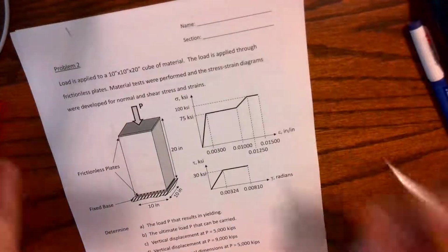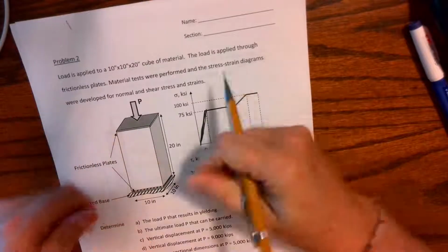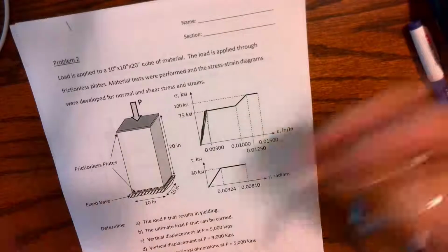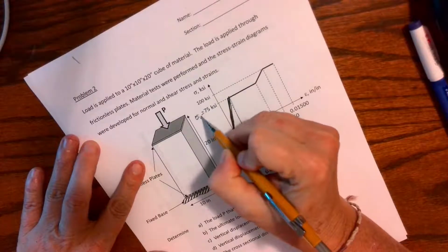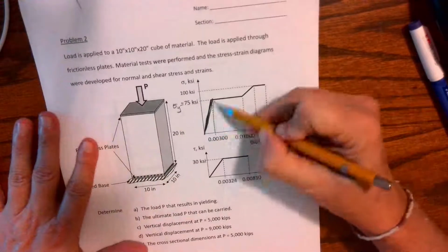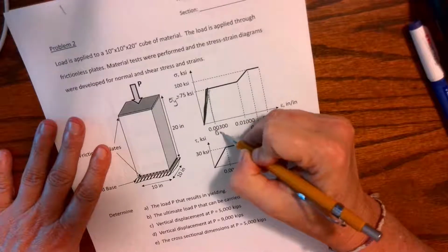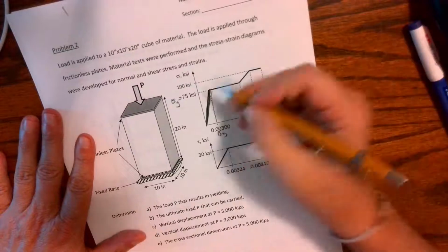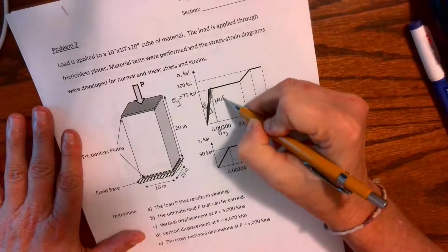So, stress strain curves. Again, elastic region is where I can stretch it and it goes back to the original shape. Stretch, original shape, stretch, original shape. So this is my yield stress. Up until this point, it stretches and goes back to the original shape. If this is my yield stress, this is my yield strain. This is where I can find E. E is my modulus of elasticity.